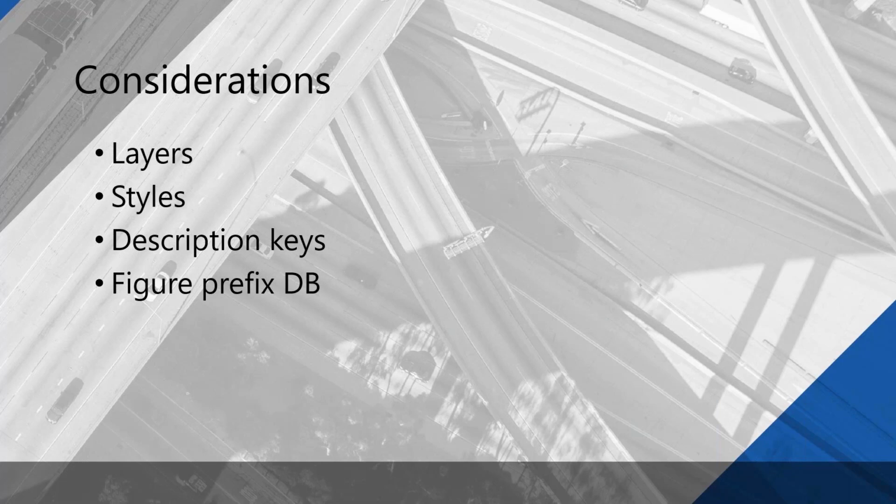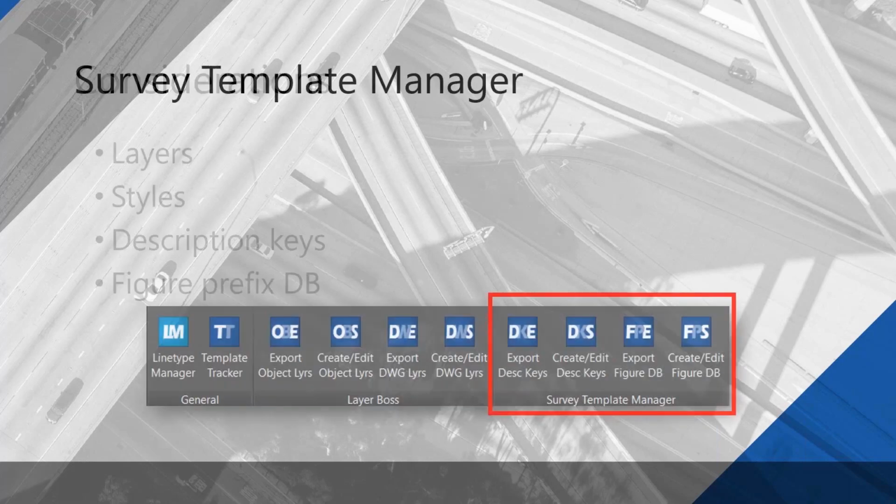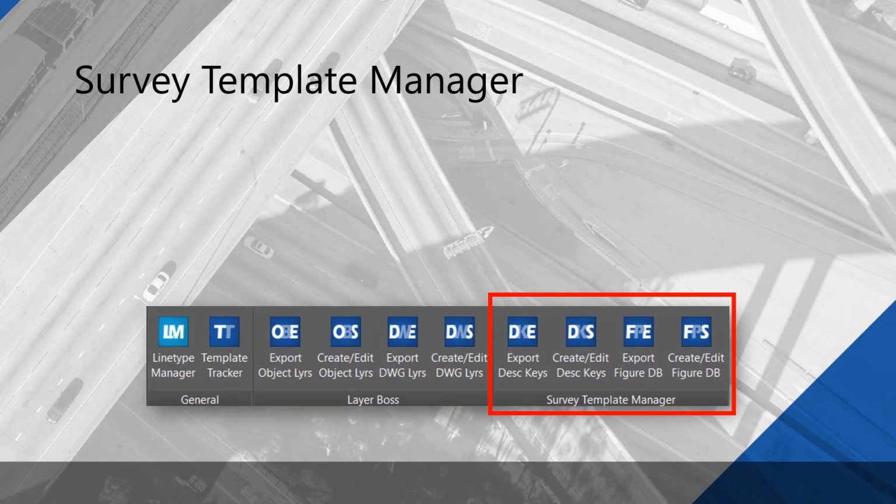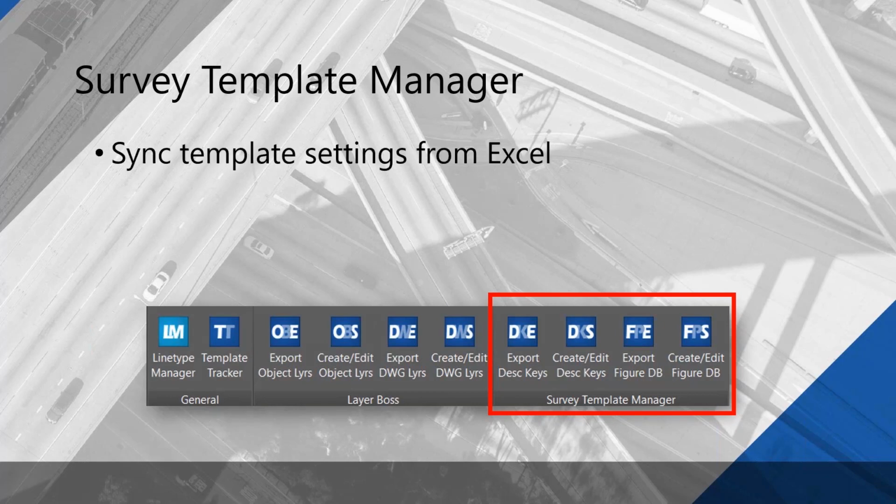There are a lot of considerations. There are layers, there are Civil 3D styles, of course, and all of those are referenced into two big interfaces, the description keys and the figure prefix database. So what the Survey Template Manager does, and that's a tool set within the CIM Manager Suite highlighted below there, is sync template settings from Excel. And why are we interested in Excel?